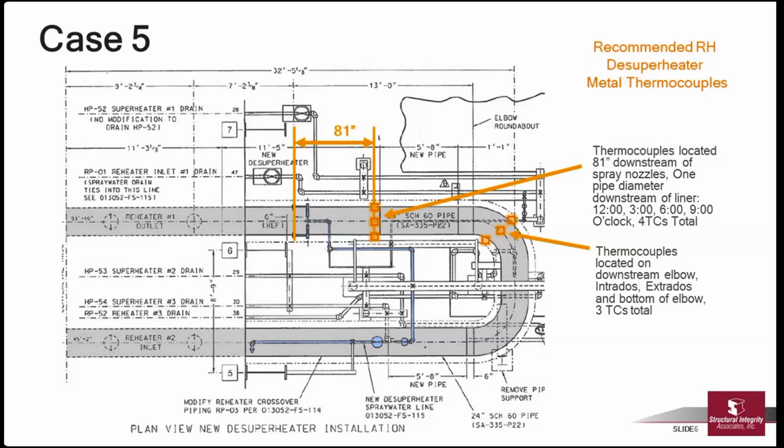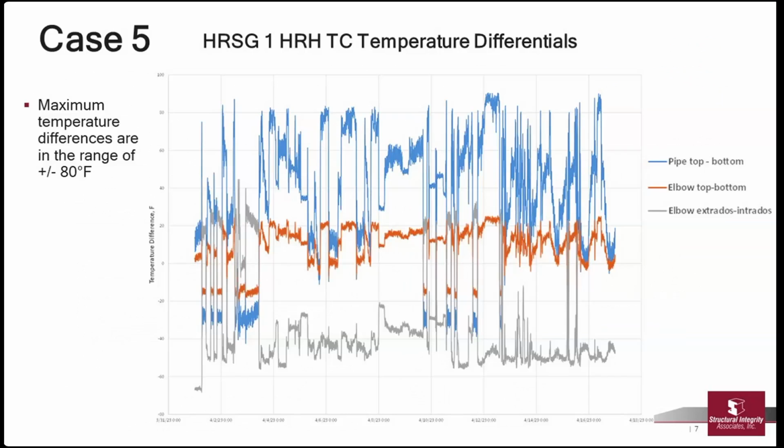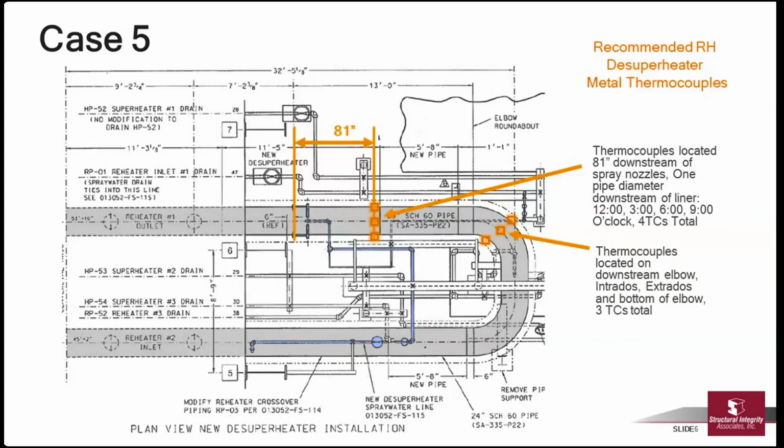So I just realized that this was a good case study of why some designs have changed over the years, though it's still not great having a U-bend. Even if you have the attemperator sprays downstream of that elbow, usually there's never enough upstream distance between that elbow. People worry about the downstream distance, but the upstream distance of sprays is also important because, as you'd expect, the flow coming around that elbow is all piled up on one side of the pipe.